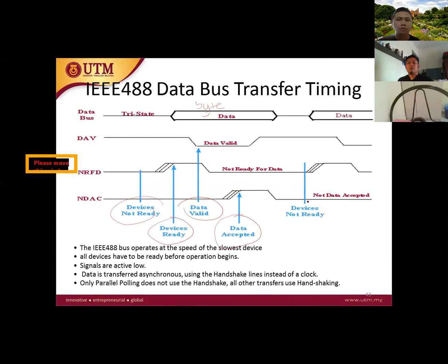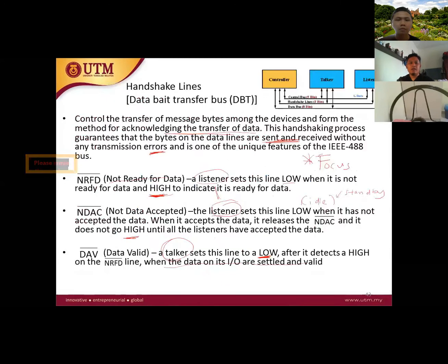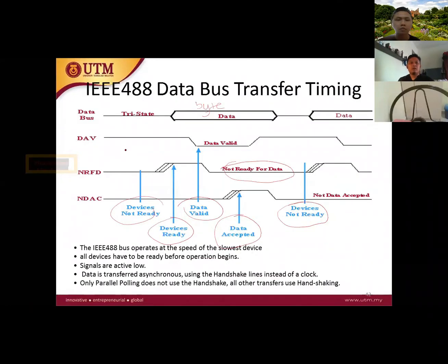And next, when NRFD is high again, at this point the device is ready for listening. Remember that DAV is only for the talker, while NRFD is for the listener, and also NDAC for the listener.